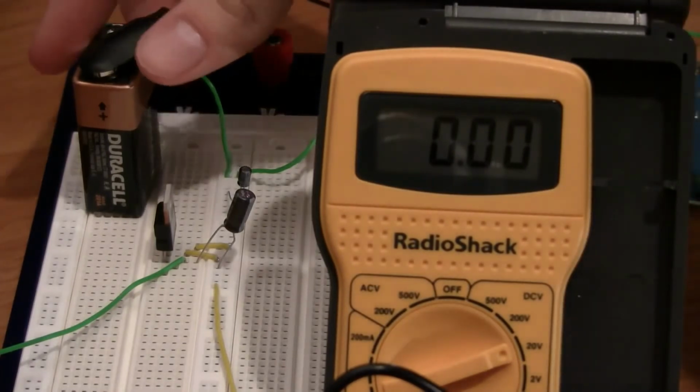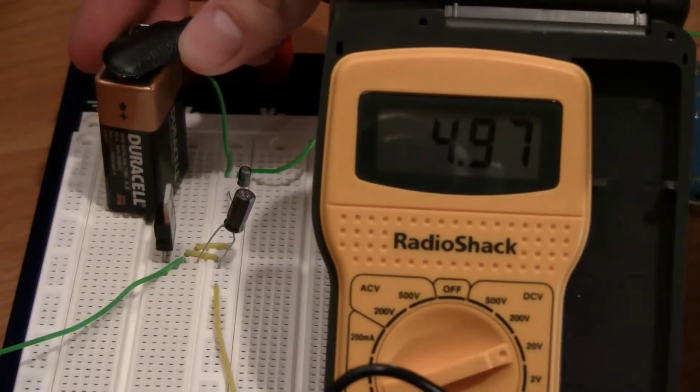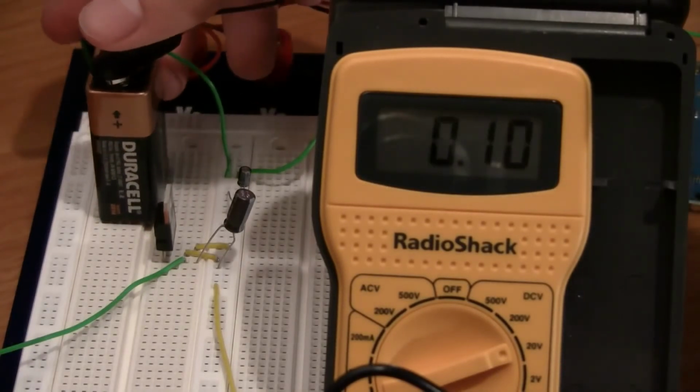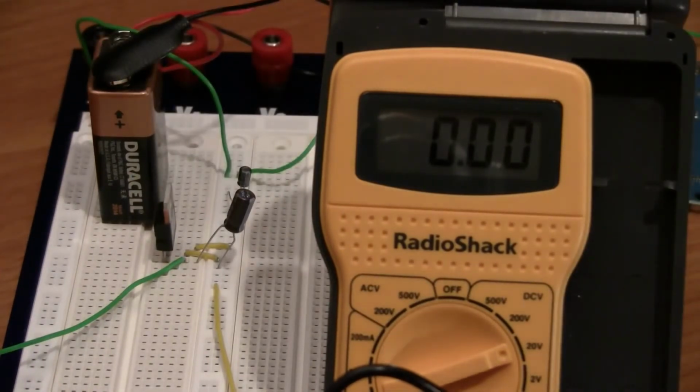If we hook up the battery, we can see that the voltage goes straight up to 5 volts, just like we want it to, and when we disconnect, it goes right back down to 0. Regardless of the voltage level of this battery, as long as it's within the acceptable range designated by the data sheet, we'll always get 5 volts out of here, which will be perfect for powering a lot of projects. Note that as this battery discharged, we'd be getting a different voltage if we were using a voltage divider, because it would change the input voltage and therefore the output voltage would change accordingly.